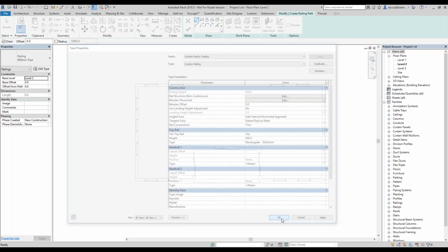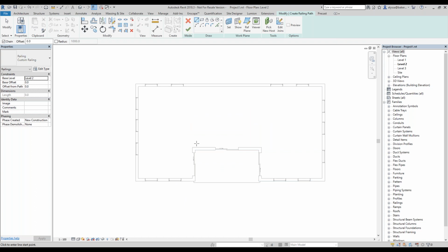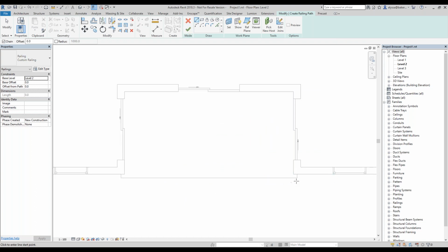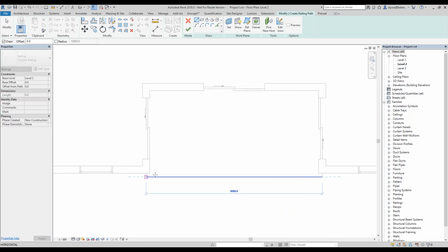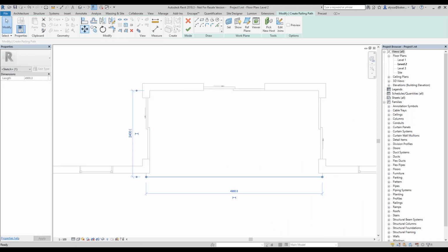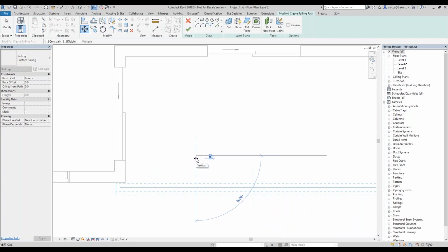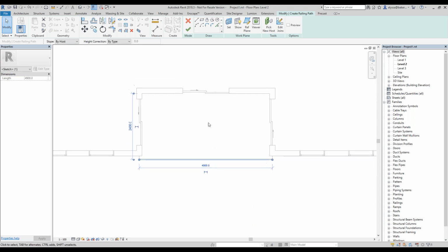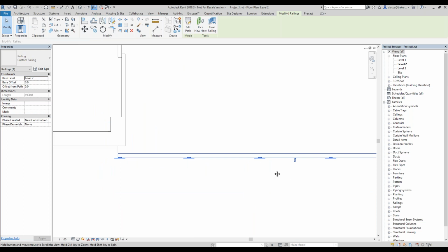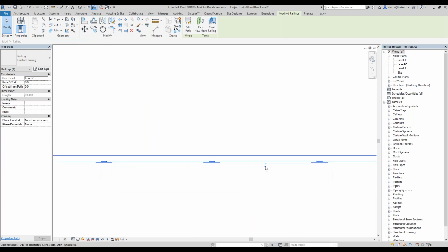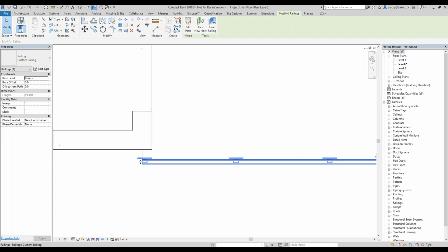So I'm clicking OK, but I'm going to draw in my balustrade. What was the distance before? I think it was 30. So let's try moving this balustrade either 40 or 30. Let's use 30. I'm drawing my balustrade path and clicking done. You can see that it's populating on the wrong side. It's fine, I can just hit this mirror, for it to be on the right side.